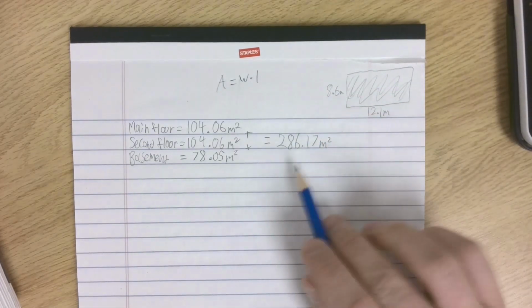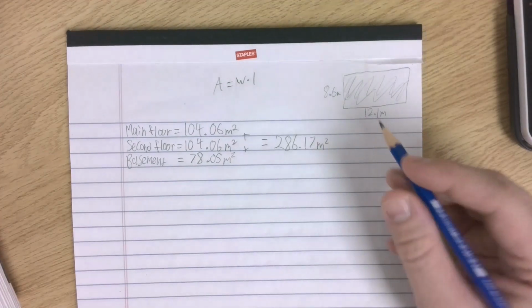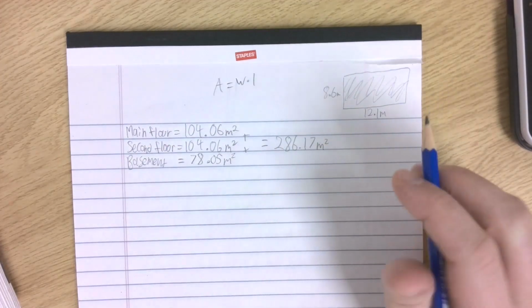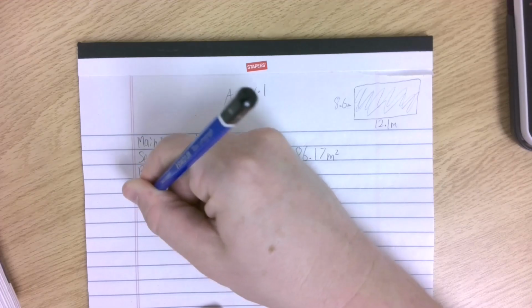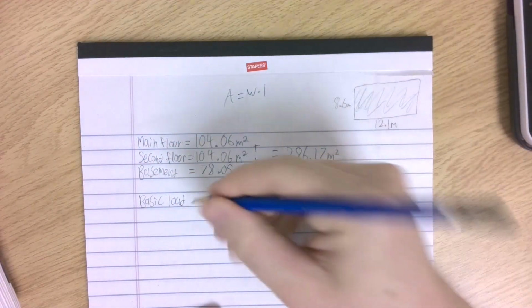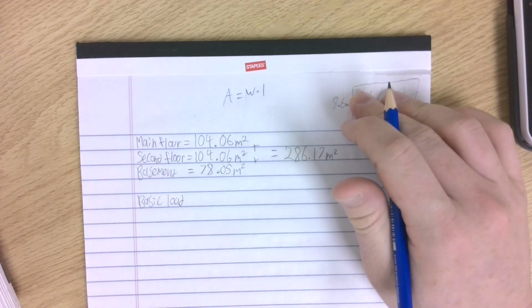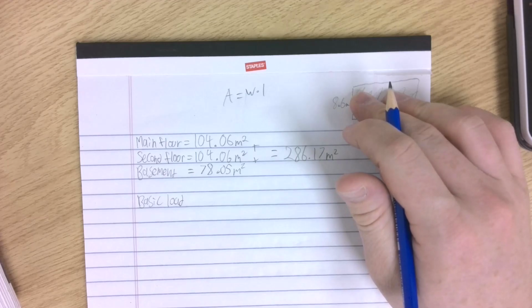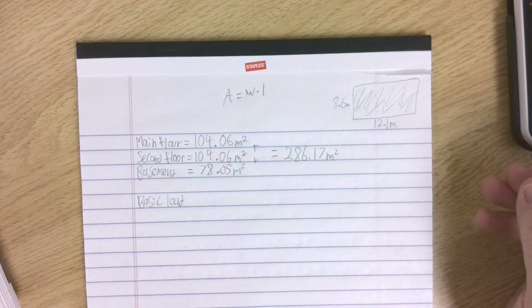Now that living area that we just figured out is what's going to count towards what we call our basic load. And how I get the basic load after getting the area of the house is going to start to look like this. So 8200 1A, item I, or 1, a basic load of 5,000 watts for the first 90 meters squared of living area. Perfect.